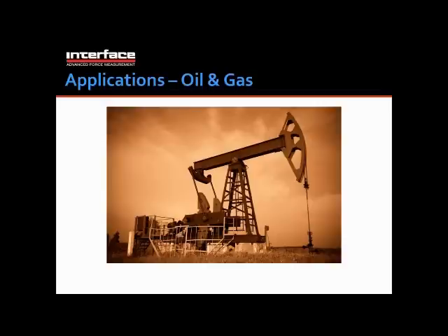Thanks, Albert. Oil and gas applications can vary quite a bit. The one in the picture there is actually a pump jack application, and load cells are used on that to give feedback to the control system that basically tells the pump jack to turn on or turn off depending on when the well is ready to be pumped. Other oil and gas applications include line tension monitoring. That can be done with low-profile load cells like we saw, maybe some load pins. There are different ways to get that measurement.